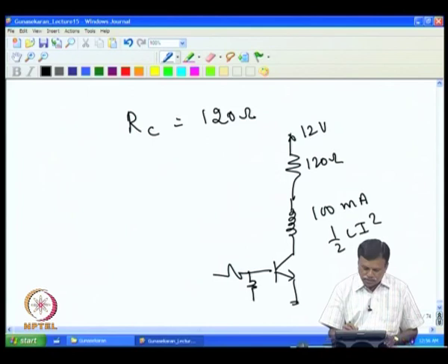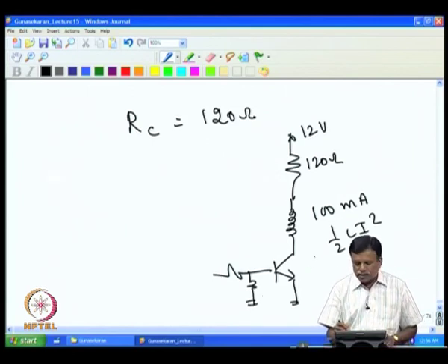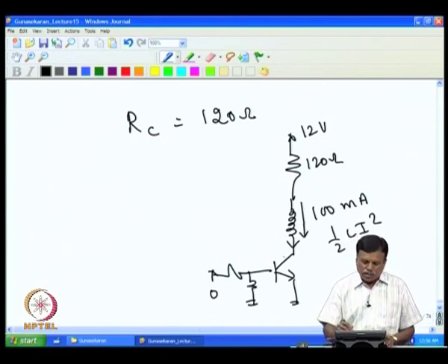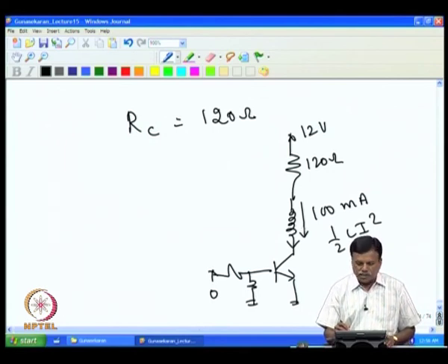It is shown this. So, when the 100 milliampere current is flowing and I switch off, that is I take this voltage to 0, then this transistor goes off. Then whatever current is flowing here cannot go anymore through this. When current was flowing, a magnetic field was built up in the coil, and that energy is stored in the magnetic field.